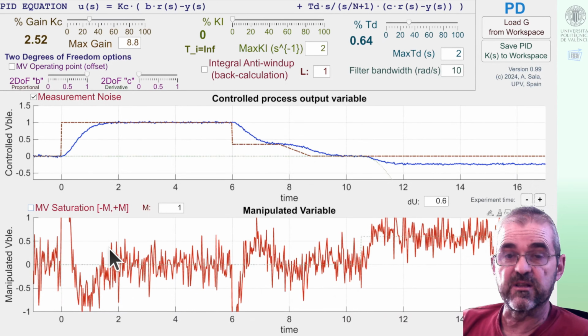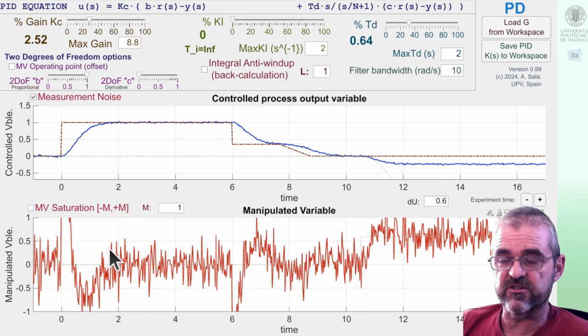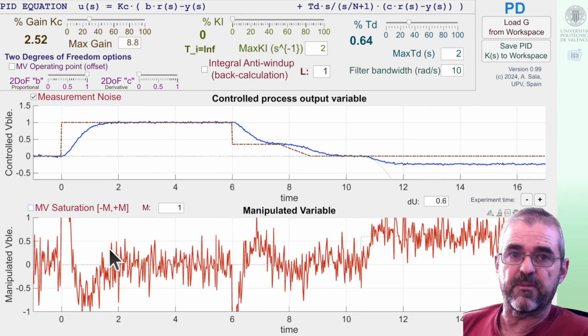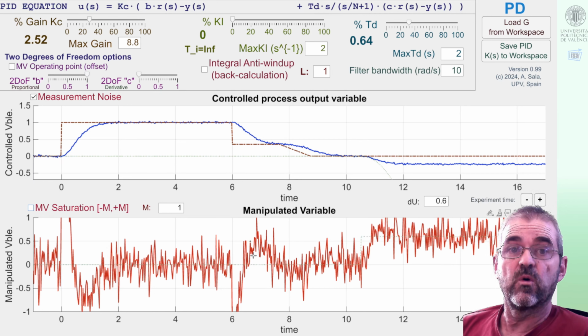Is this good or bad? Well, it depends. If we are moving mechanical systems, this may be bad because we may induce high frequency vibrations that excite some resonances that break some things with fatigue. On the other hand, in some applications, it's good to overcome stiction because of Coulomb friction, because continuously bumping up, down, left, right, the thing I am trying to move will diminish the deleterious effect of Coulomb friction stiction. So it depends on your application. You may be happy with this or not.